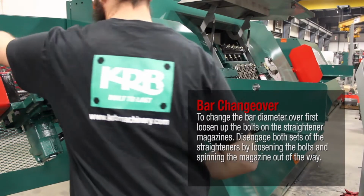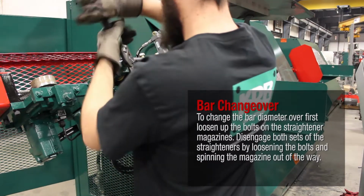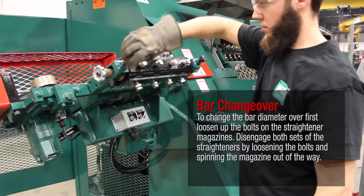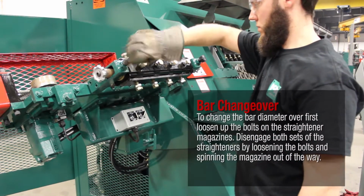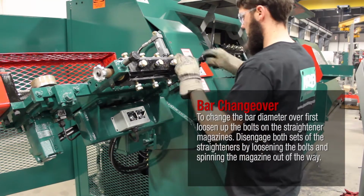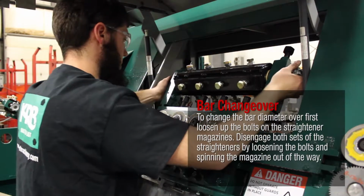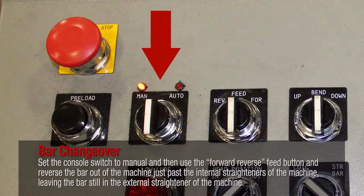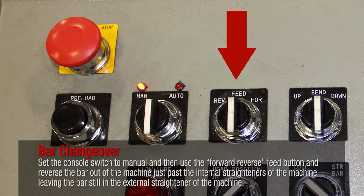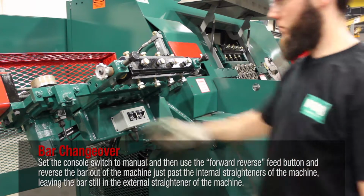Bar Changeover. To change the bar diameter over, first loosen up the bolts on the straightener magazines. Disengage both sets of the straighteners by loosening the bolts and spinning the magazine out of the way. Set the console switch to manual and then use the forward-reverse feed button and reverse the bar out of the machine just past the internal straighteners of the machine, leaving the bar still in the external straightener of the machine.